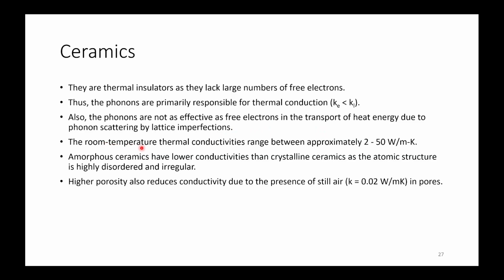The room temperature thermal conductivities range between approximately 2 to 50 watts per meter Kelvin, and amorphous ceramics have lower conductivities than crystalline ceramics as the atomic structure is highly disordered and irregular. Now higher porosity also reduces the conductivity due to the presence of still air. So the air will be trapped inside those pores or certain gases will be there. So these will have very low conductivity. So it will reduce the entire conductivity of the material.